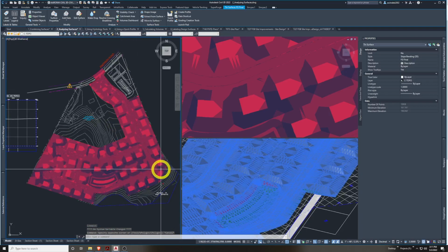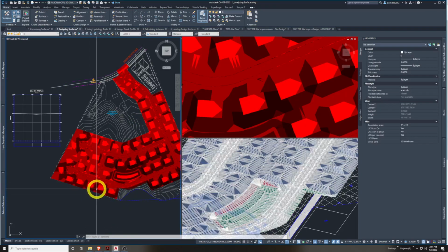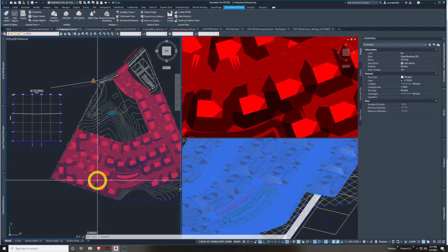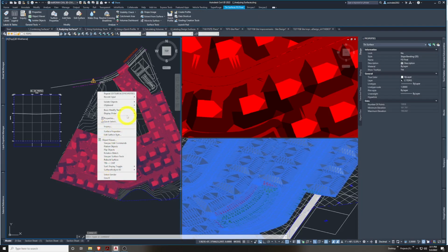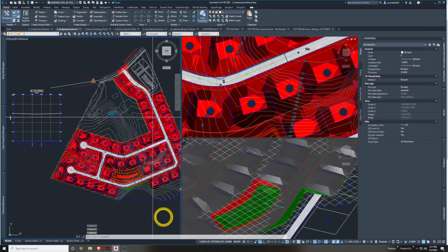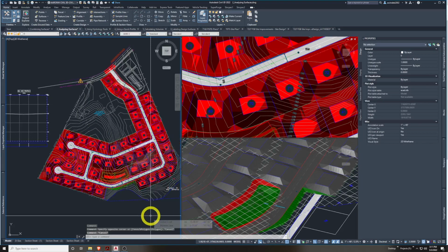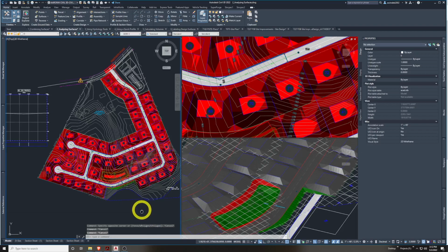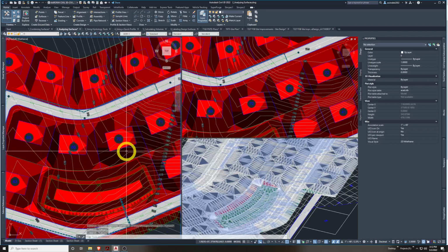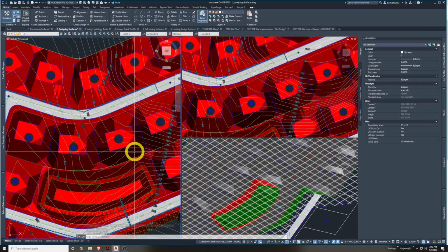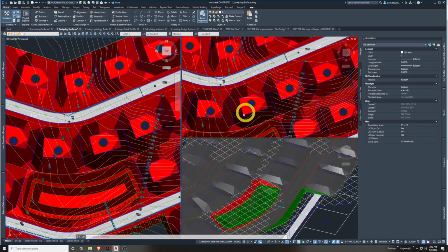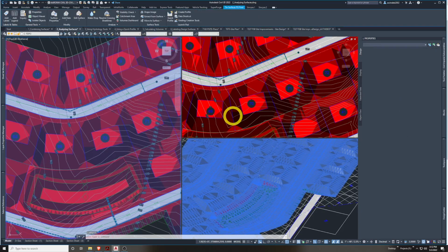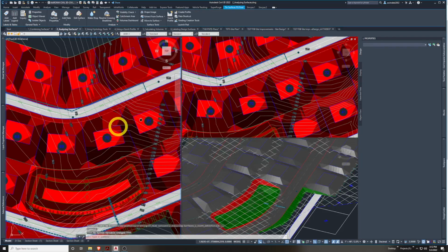This is our big thing. So our surface is kind of in the front. Let's pick it and right click, and this is for any Civil 3D object. New Civil 3D objects always go to the front by default. We're going to send it to the back so we can actually see things under it. And we're going to go into one area of this subdivision, hit escape. Let's go to the center of lot 70. It was also in the upper right viewport already, but either viewport.